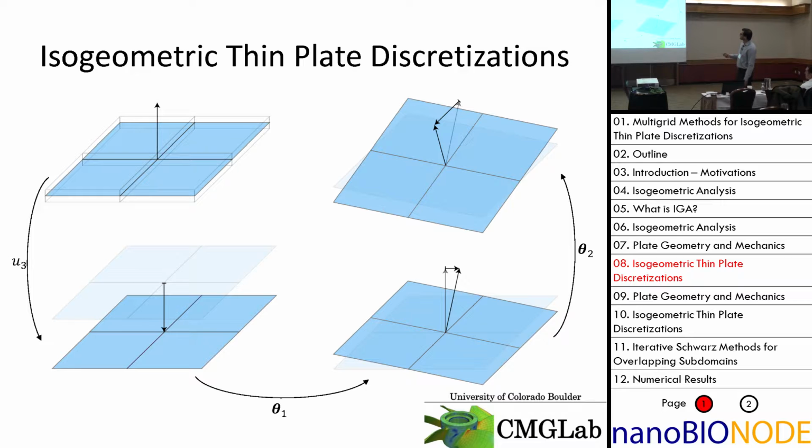It's a little difficult to see, but the undeformed geometry is actually right here. And we can see we've just displaced the mid-surface downwards. And then to account for rotational effects, what we do is we just do a vector component addition here. And so we add vectors to cause these planes to rotate. So if we want to get a rotation about our xc2 direction, we just add a vector in the xc1. And if we want to get a rotation about the xc1 direction, we add a vector in the xc2. And this is what we use when we're creating our displacement profiles in plate modeling.